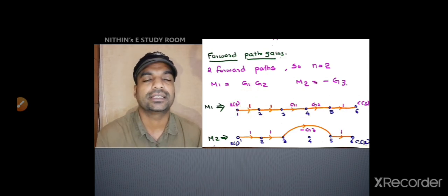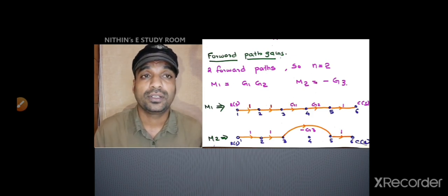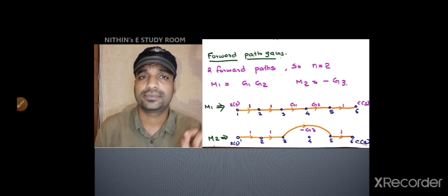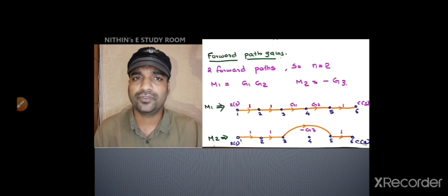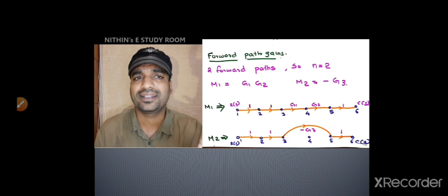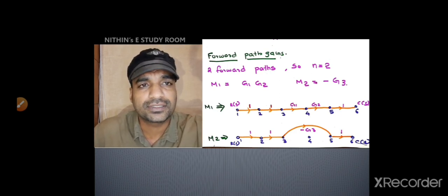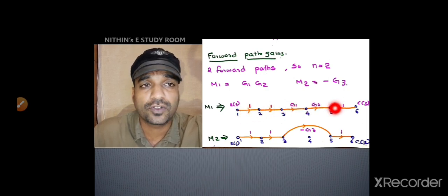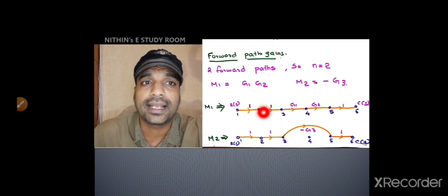In that we are checking whether the terms in delta are touching or not. Anyhow, in delta there is 1 minus L1. That was the basic expression of delta we obtained. The value of L1 we know. For the time being I am taking it as loop 1, L1 only, not using the value. And this is the first forward path. I am asking whether the first forward path is touching loop 1 or not. Yes, it is touching, because loop 1 lies here.